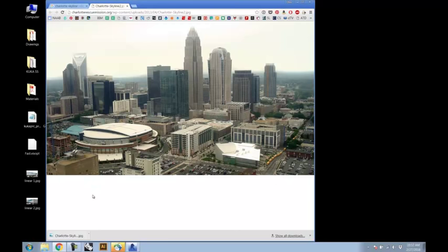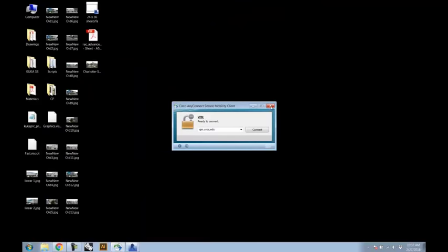It's important to think about the perspective, and then I would say I'm probably close to 400 feet in the air. It looks like I'm about even, maybe a little bit higher than Grant Thornton. So I'm just trying to estimate roughly where the camera is in this view, so that I can place the camera in Revit in a way that'll work relatively well.